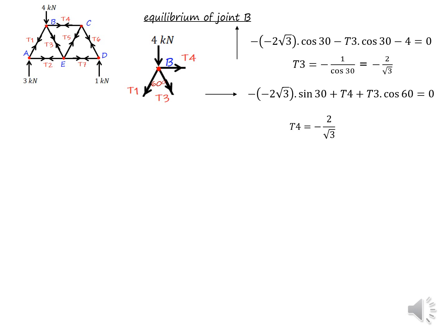number is because it's the other side of the direction that I consider, which is opposite to the direction that the force is acting, so it's minus. And T4 is in the direction that we consider, the arrow you can see, so that is positive T4. Also the force component from T3, that is T3 cos 60, is again in the direction that we consider, which is positive.